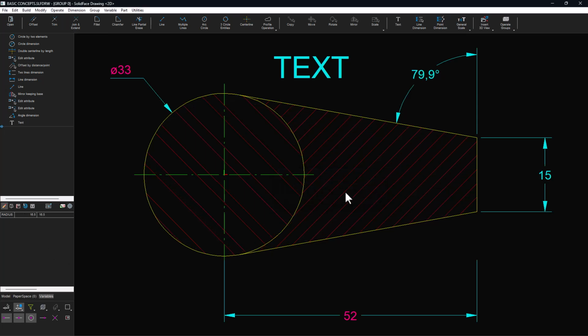In a given active group, it is possible to define any number of variables. We can create global variables that are visible on all groups, but we will not demonstrate them here. When creating a parameterization of an entity, you can indicate the dimension with its current value, or indicate the associated variable. For instance, in the circle dimension, indicate that it should show the geometry-associated variable.